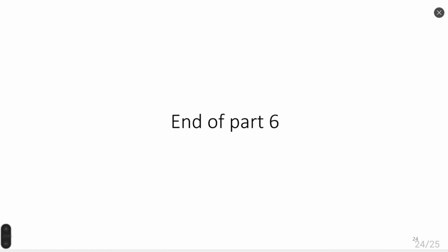But the problem persisted. The strange part is that when the problem persisted, I suspected it wasn't the mesh. So I tried testing with another simulation method. I tested it in the standard K omega model, just to see if a different result would come. And when I tested it in this model, the simulation converged perfectly.